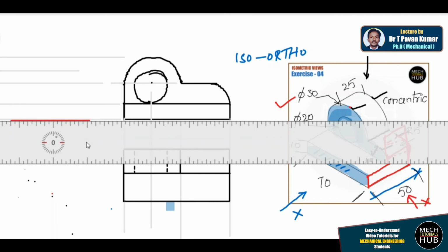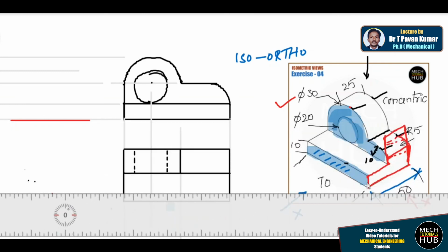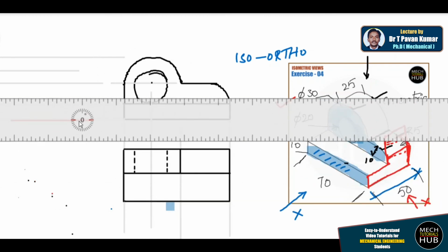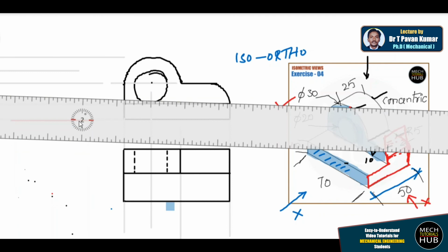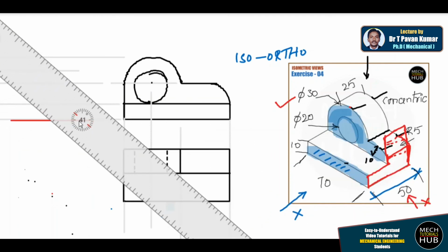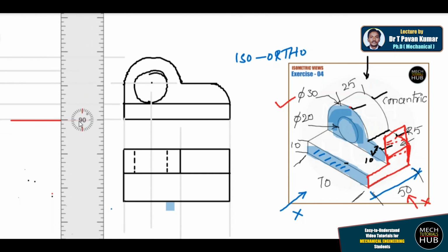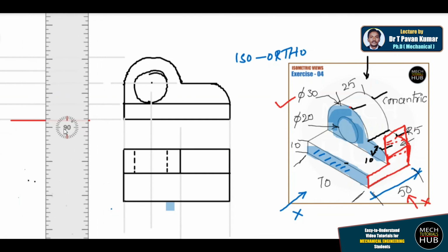These two will get joined, because here the vertical is joining with the top and there is a straight vertical going up to the top. So let me rotate the scale to 90 degrees, align with the end point, and draw a line till the top.